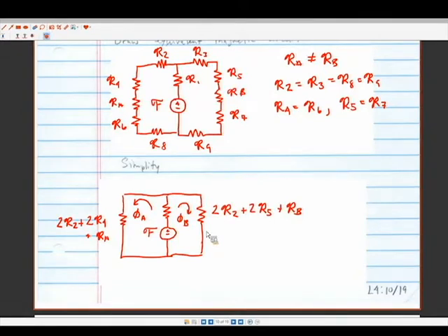Okay, so this is your standard current divider or parallel circuit here. So we have phi, which is going through the magnetomotive force. That's the flux for the entire circuit. That is then being divided or split at this node here, and that's split into phi A plus phi B. So Kirchhoff's current law holds here as well. That means that we have phi is equal to phi A plus phi B. So you can leverage that. Kirchhoff's voltage law works for this. There are many ways that you can leverage the knowledge that you have from electrical engineering classes for these problems. So we're going to use the form of a standard current divider.